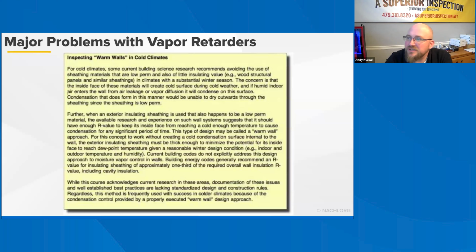In hot, humid regions, walls must dry towards the interior. Homeowners should avoid non-breathable finishes like vinyl wallpaper or vapor barrier paint. Vapor retarding materials on the inside can cause condensation issues. Use semi-permeable materials such as unfaced fiberglass batts with permeable interior paint.